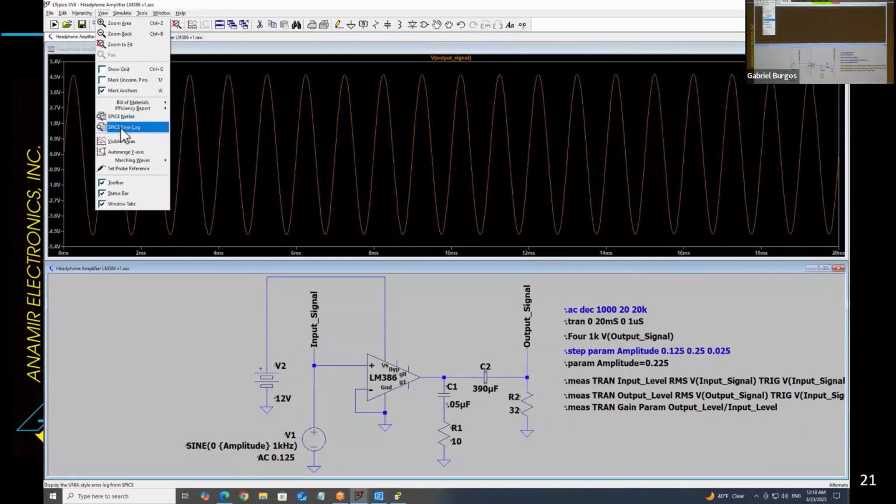I work on airplane radios in Hawaii, and people are always asking me to make microphone circuits for them. I was mostly using transistors, and I couldn't figure out how to get a small microvolt signal from a microphone into an amplifier. With an op-amp it's so easy, but I don't understand how you bypass the bias limit with the DC power supply without using a capacitor. Is it possible? Yeah, you use resistors to provide a bias that sends the transistor into conduction.